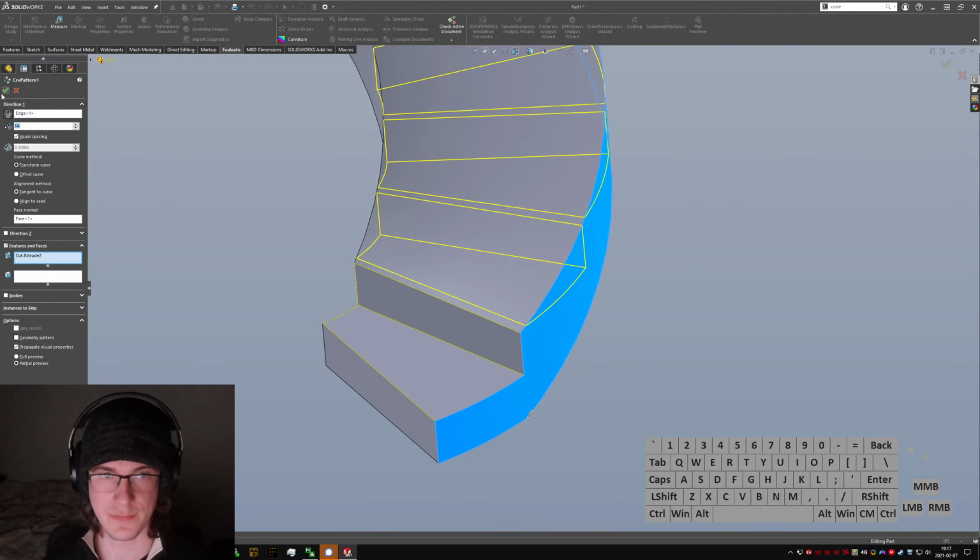What if we just tell it to do a geometry pattern instead? Yeah, okay, that breaks. This, because it's trying to cut a face that's going to end up right on plane with that face, it's going to complain pretty much no matter what. Although now that I'm looking at it... No, 14... Oh, can't do geometry pattern. 14, does it cut that face successfully? It does. Okay, so it's jacked up for some other reason. I had this really awful idea where I could cut half of the steps in one go and then cut the other half in the next go, but there's no way that doesn't break horribly.